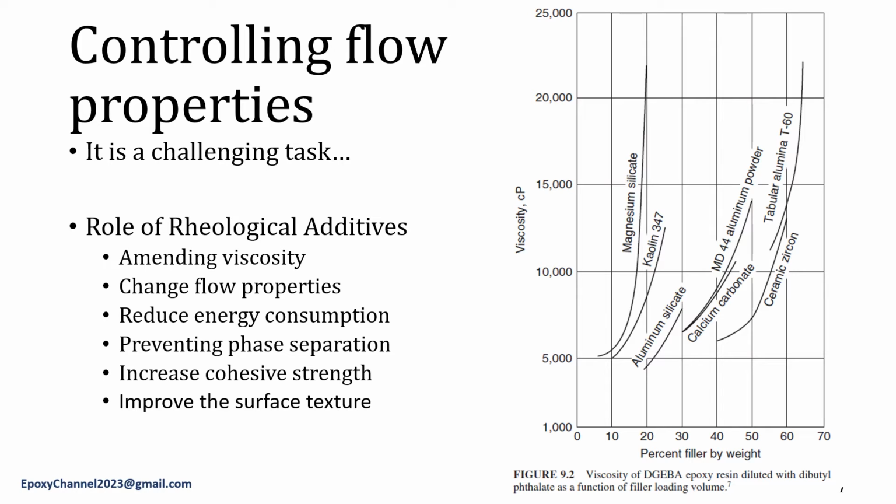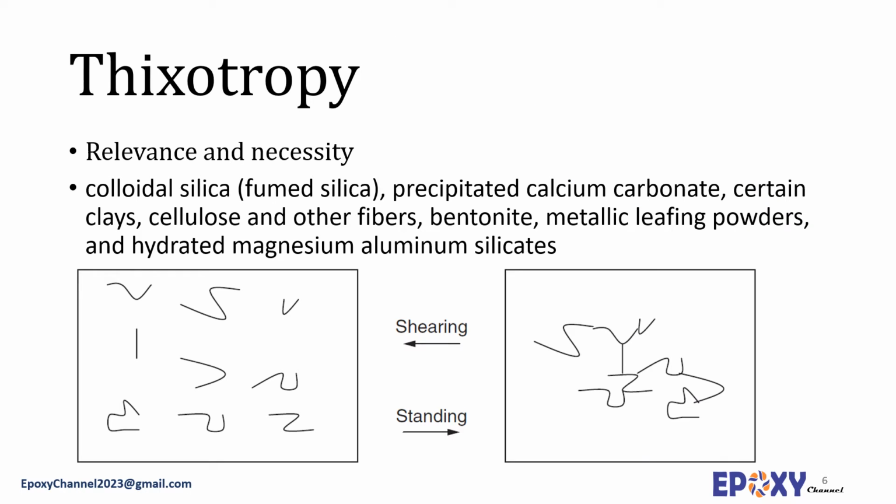Figure shows the obtained viscosity versus weight percent of various fillers in diglycidyl ether bisphenol A epoxy diluted with dibutyl phthalate. The other role of fillers is to control the thixotropy to avoid sagging.